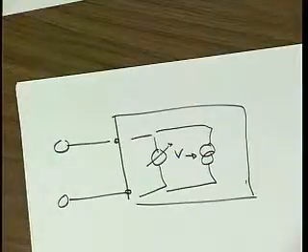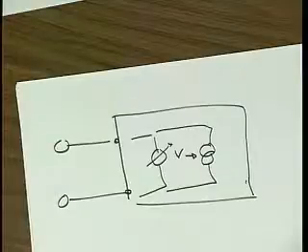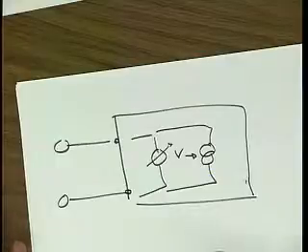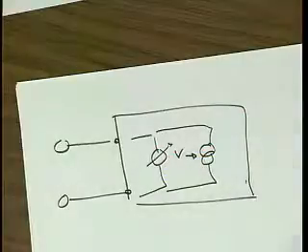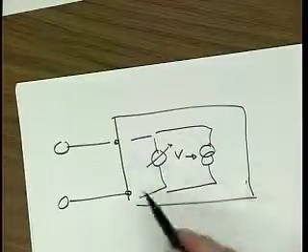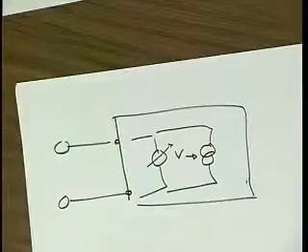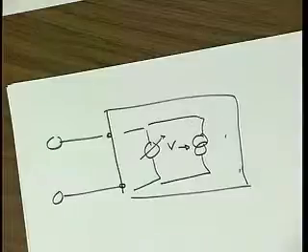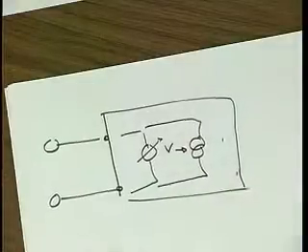What do you think the problem is? Actually, this is not an uninteresting thing. Because if we could build resistors with less noise, we could build circuits with less noise than we ought to get, and then because noise is seen as linked to power, we could presumably make circuits with lower power. Great, huh? Well, the reason that doesn't work is that all this junk that you put into this box needs power. So either you put a battery into the box, or you add a power supply, and the whole neat idea goes out.